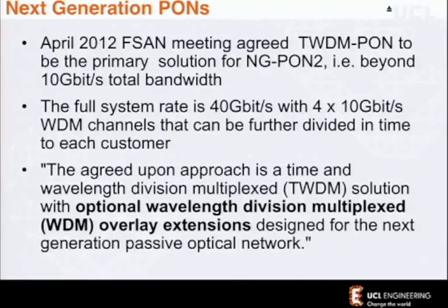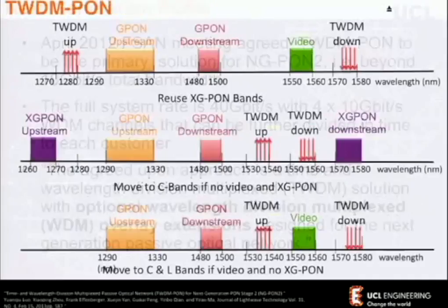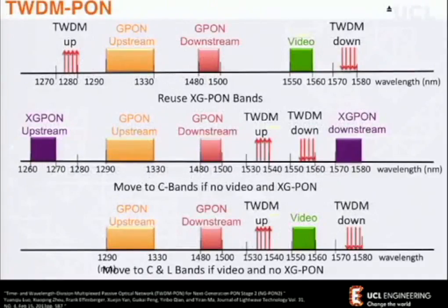But if you're going to take up 1 gigabit, 4 gigabits, 10 gigabits even for a CPRI interface, you're taking up quite a lot of the bandwidth that was of a traditional link. You're squeezing the number of fixed line customers that are going to be on there. So maybe that's not the only way it's going to go. There are other ways of doing it. You can put overlay channels into PON.